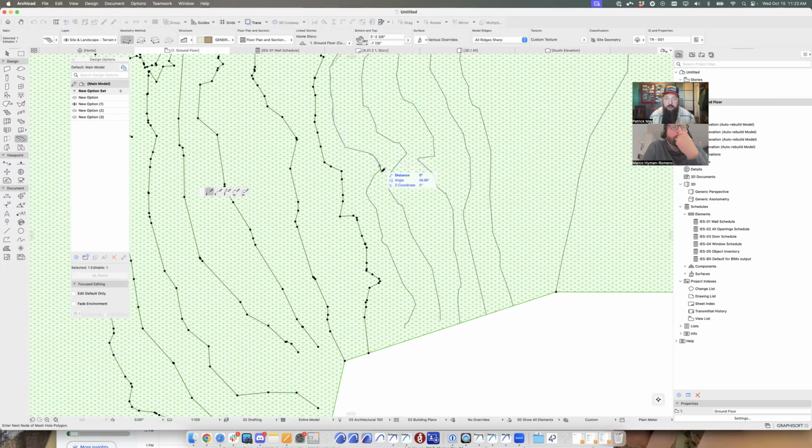You do have to click inbound from the mesh edge. I want that to run to the edge. If I were to start on the edge, it activates the pet palette. So you can't start placing a contour by clicking on the edge, but you can start by clicking inbound from the edge.